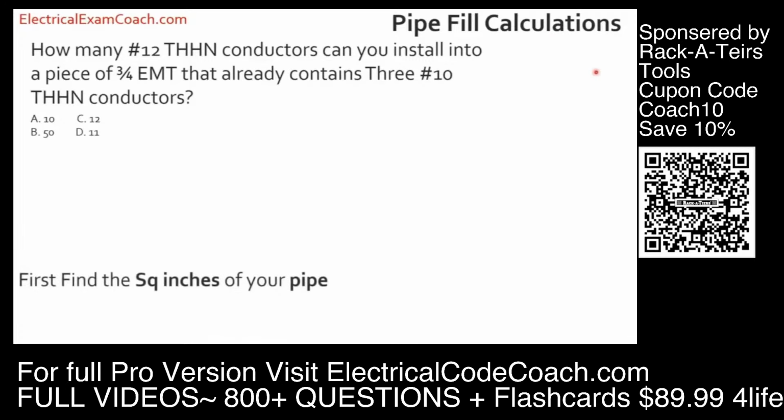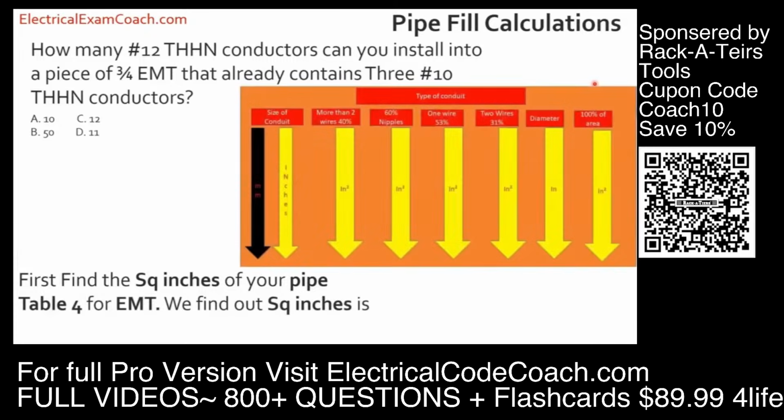The first thing we're going to do is find the total area that we have to work with. To do that, we're going to head to Chapter 9, Table 4 for EMT. When we get there, the first thing we do is make sure that we're in the right type of conduit. Then we start on the left-hand side and find our trade size, and we go down to 3/4. Then we cross over to the "more than 2" column because our question deals with more than 2 conductors, so we pull from the 40% column. That lets us know that our starting available area is 0.213 square inches.